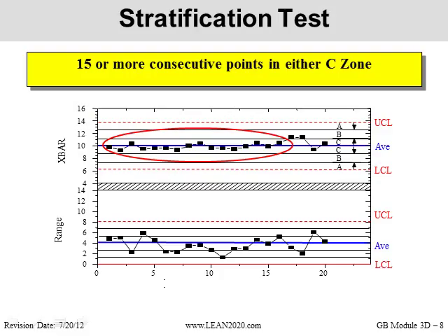Now, a couple things may cause this. First of all, if somebody is just pencil whipping a chart and giving you what they think you want, it's going to look something like this. There's not that normal variation. Something's causing that, and it's an operator or technician giving you what they think you want. And really, what you want is accurate information from your process so that you can react to and improve that process.